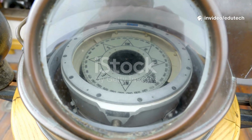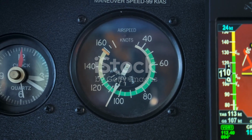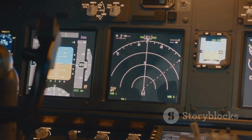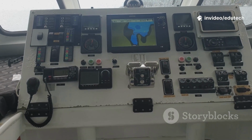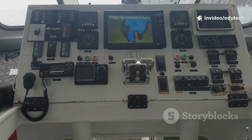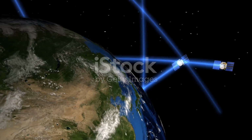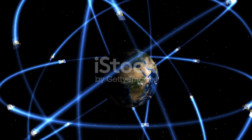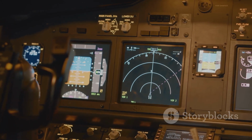Traditional navigation instruments include a clock and a magnetic compass. Along with the airspeed indicator and wind information, these can be used to calculate navigational progress. Radios and instruments sending locating information via radio waves have replaced these manual efforts in modern aircraft. Global positioning systems, GPS, use satellites to pinpoint the location of the aircraft via geometric triangulation. This technology is built into some aircraft instrument packages for navigational purposes.